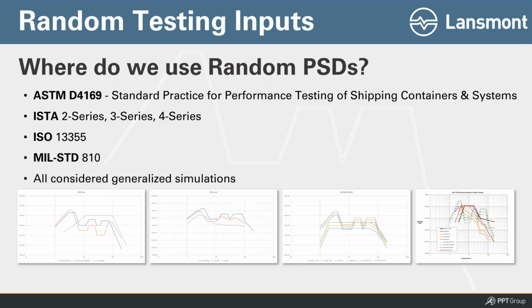Especially within ISTA, we describe those PSD profiles as general simulation profiles. They're generalized vibration profiles that simulate the energy content that you would experience if you ship using different modes. I'm just showing a broad cross section: ISTA 3A, ISTA 3H, ASTM 4169, the ISO 13355.